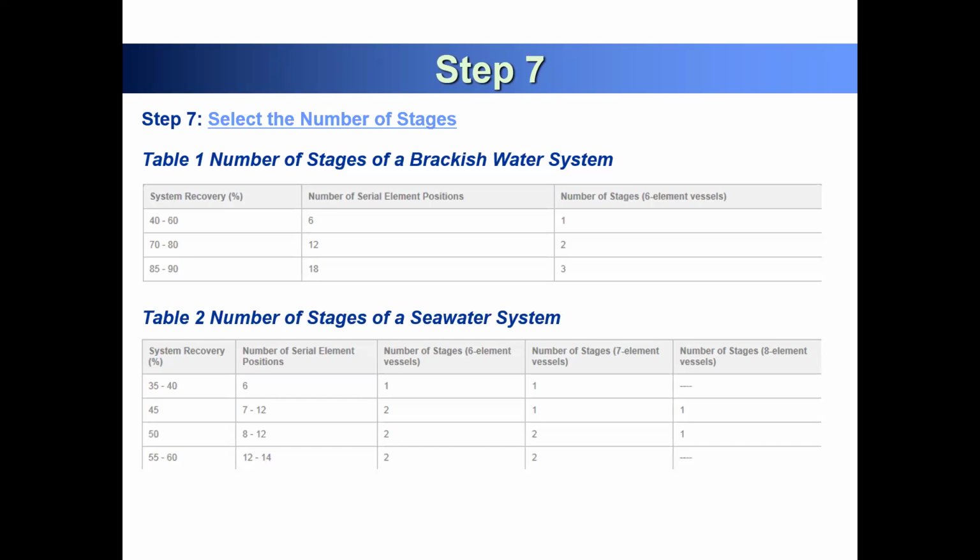In the second stage, you can use a ratio of your membrane module elements and pressure vessels of 8 to 2, or you can have 7 and 3. A different ratio you can utilize to achieve high recovery of your seawater desalination. So depending on your system recovery, you can select first stage or second stage.